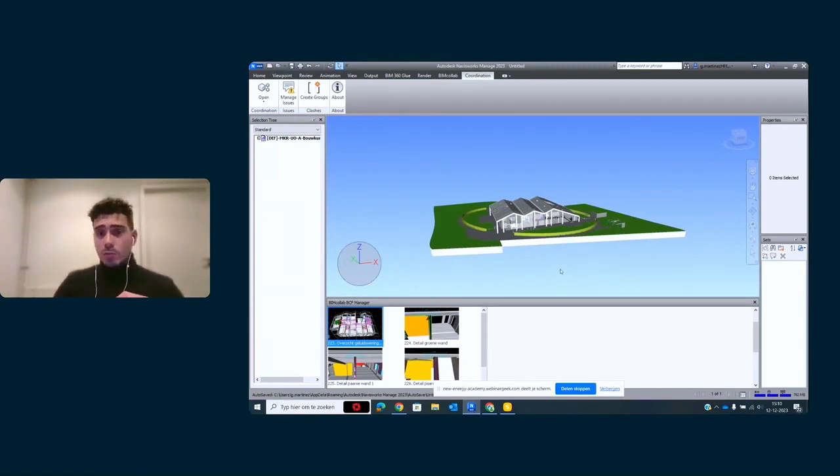So we have the possibility to use two different tools, Navisworks and Solibri, and we use Navisworks to make the clash definitions, and depending on how many clashes, we connect the clashes to BIM Collab. This way we communicate with the different partners, and the communication goes through the model, and it's not necessary to use email or other types of communication.